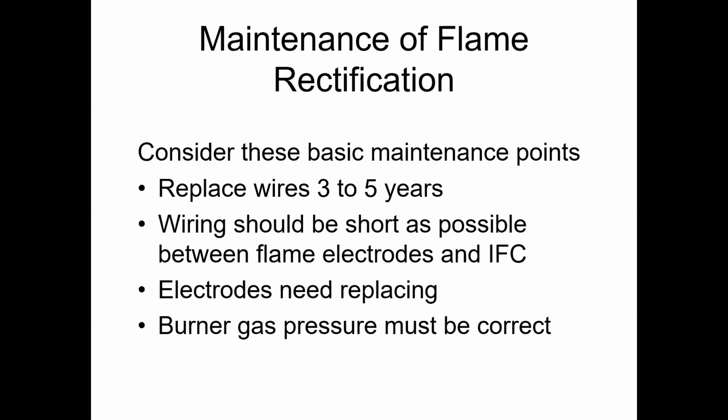Again, it's saying keep your wire short. That is definitely a main thing you want to do because we're dealing with DC voltage. It's going to need large gauge wire, traveling a short distance. You do not want to run this longer than what the manufacturer already has it set at, because this will be wired from the manufacturer. You're not going to have to figure out how to wire a flame rectifier in, and if not, you can always look at a wiring diagram. It'll show you exactly how everything's wired in.